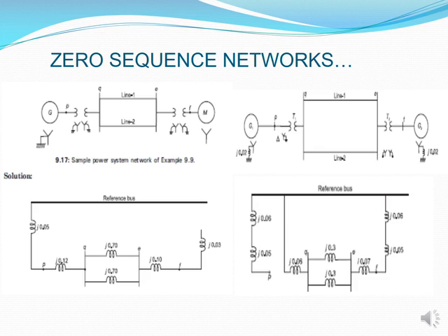Then if you look at the second part of my system, you can see that I've now got impedances from my generator sources. Those get multiplied by 3, and then I just show what my generator normal impedance was going to be. And then I also show that from generator 1, I've got an open point because when I go into the transformer, I've got a delta scenario. That's why we open it when you come in. And then the other part, because it's earthed, I connect it to my reference bar.